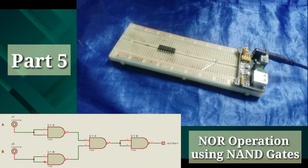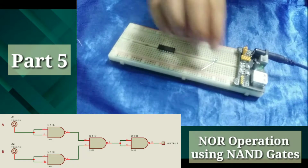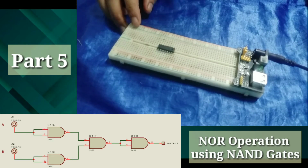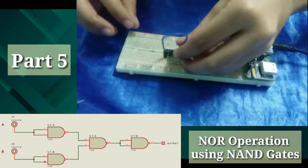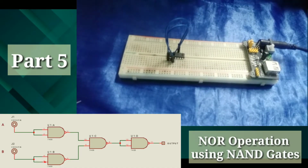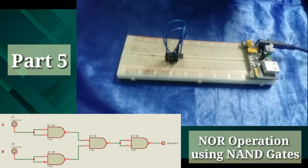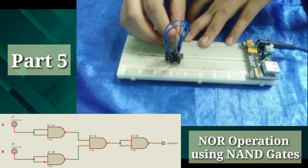Now, for our part 5, NOR operation using NAND gates. Still, we will be needing a 7400 integrated circuit and the materials that we needed before. So, in the circuit, you can see that pins 1 and 2 of the IC are connected. Then, pin 3 is connected to pin number 10 of our integrated circuit. So that's 8, 9, 10. Then, pins 4 and 5 are connected as well. And pin 6 is connected to pin number 9 of our integrated circuit.